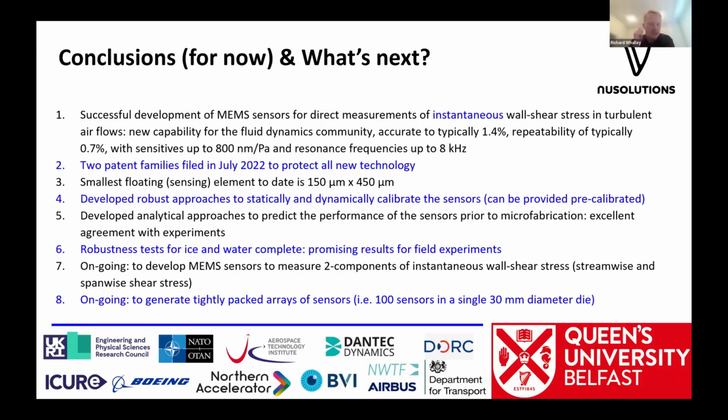Our smallest floating element size is around 150 microns by 450 microns, but ultimately we'd like to go smaller than that if we could. We've now got some nice robust approaches to statically and dynamically calibrate the sensors. So ultimately the sensor can be provided pre-calibrated. And we've got a very good idea about how our sensors will perform before we put them into production because of the nice analytical approaches that we've developed. They seem quite robust to ice and water, so promising for field experiments.